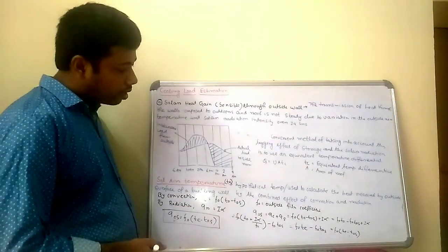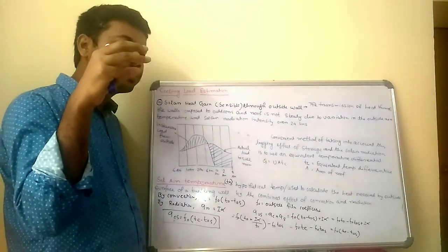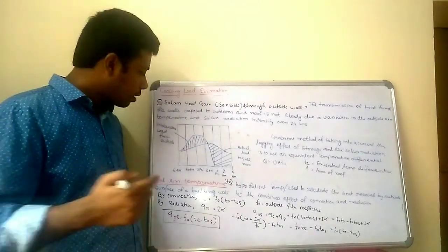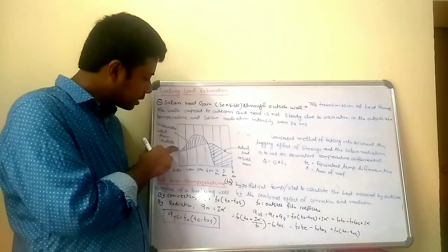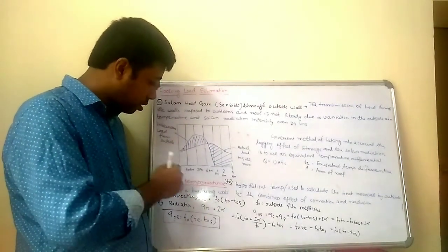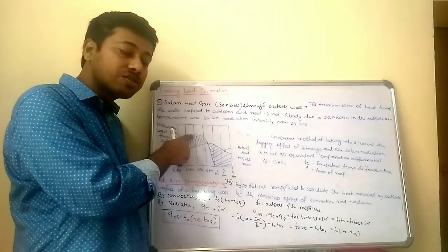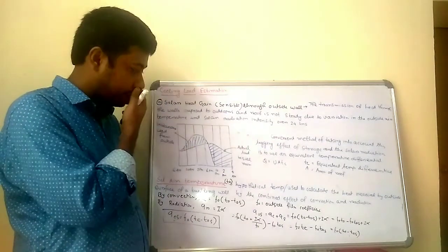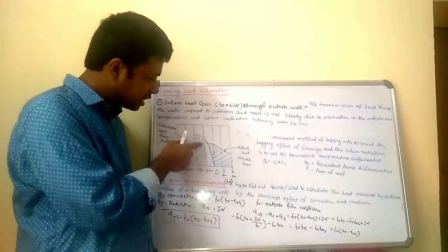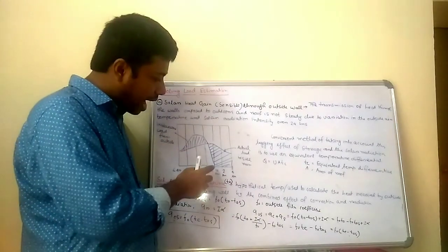And 4 a.m. So you can see that when the radiation comes out from the sun, it will fall onto your roof or outside wall. So obviously the temperature will increase as time goes on. At 2 p.m. it will pick up the maximum instantaneous load from the outside, and it will fall down at around 6 p.m. It is lower, but the negative indicates that the temperature falls down at around 10 p.m.